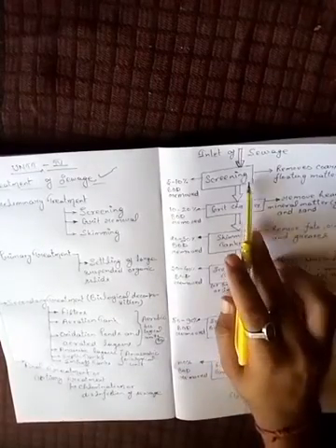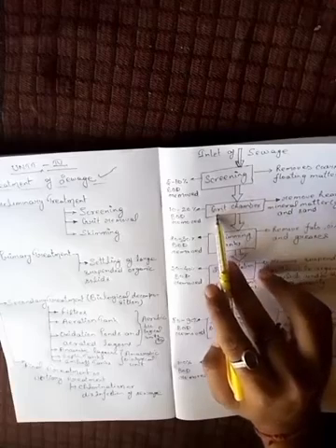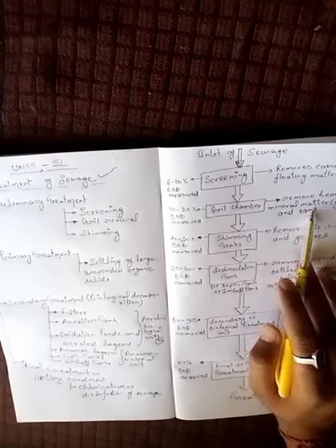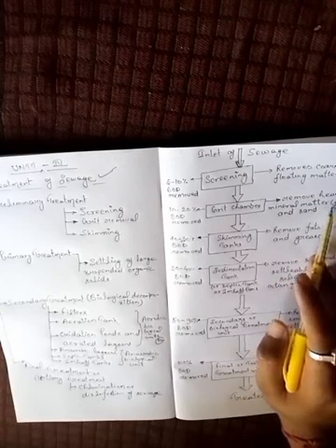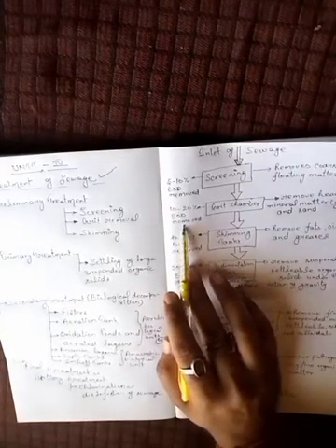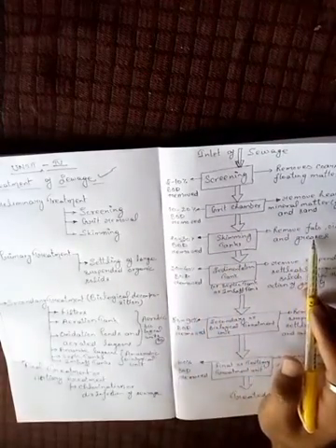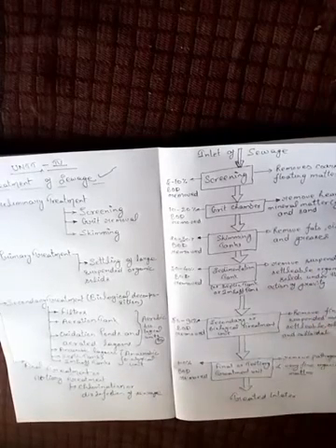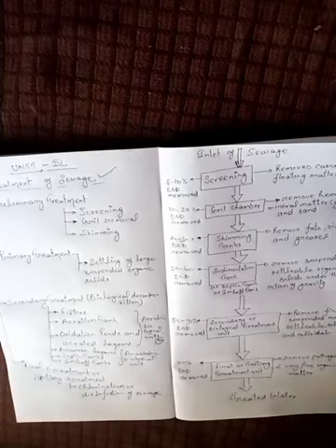Next, the sewage treated through the screens goes to the grit chamber. In this chamber, heavy minerals or matters are removed by the grits or various screen-type structures. In this step, 10 to 20% of BOD is removed by this chamber. After that, skimming tanks. In this step, fats, oils or greases are removed from the surface of the sewage. In this step, 20 to 30% of BOD is removed.